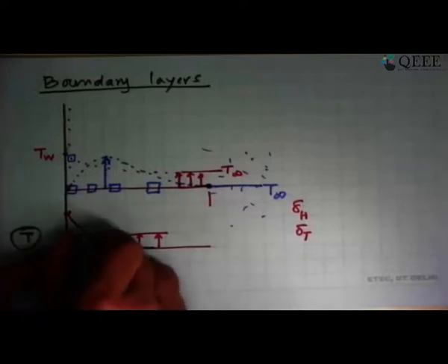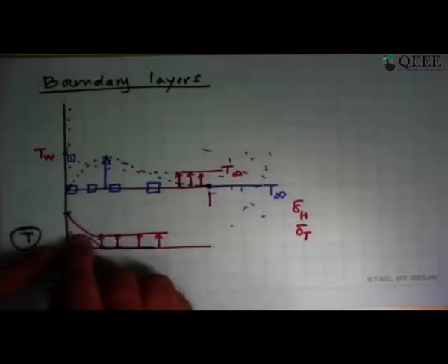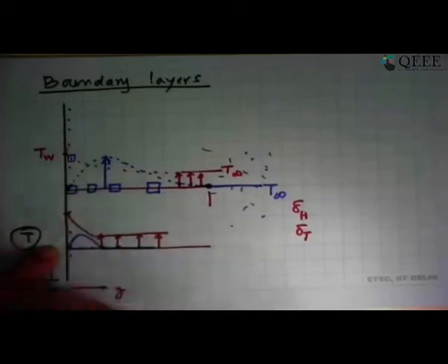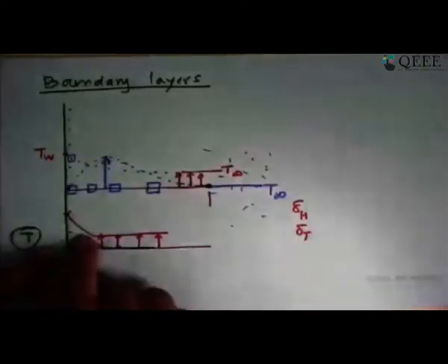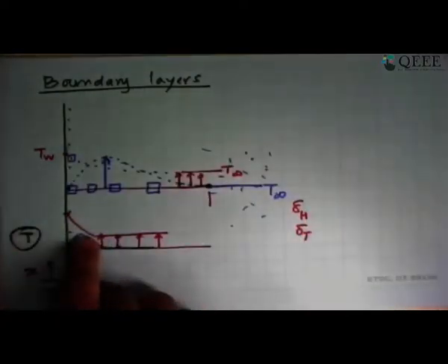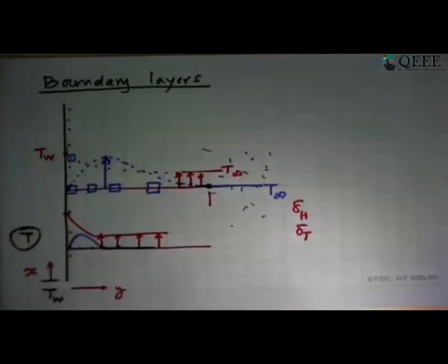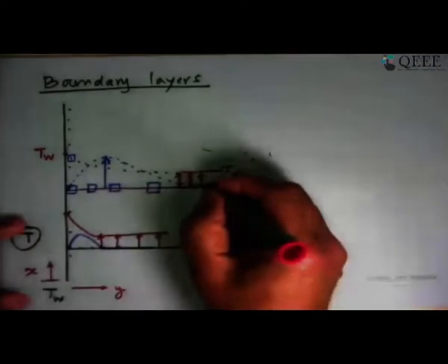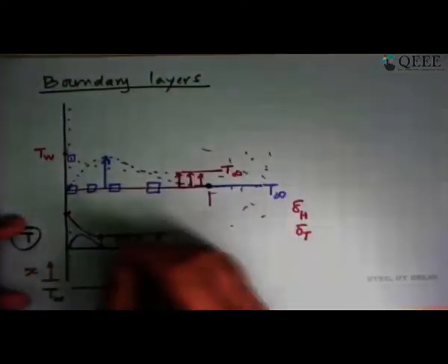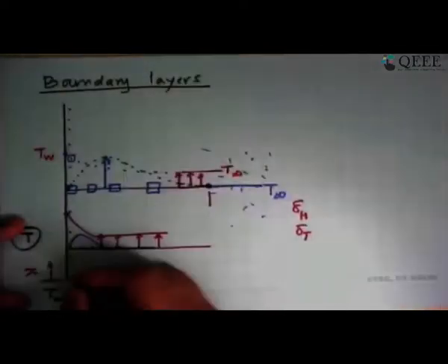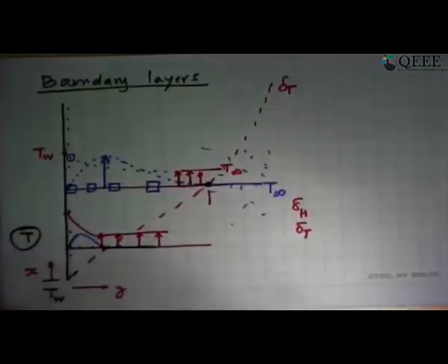Inside this thermal boundary layer, there is the peak velocity, which is proportional in some sense to the temperature gradients that are formed inside the thermal boundary layer itself. So two things have now developed: the point up to which this temperature gradient is felt, we can join those points, and that becomes a thermal boundary layer.